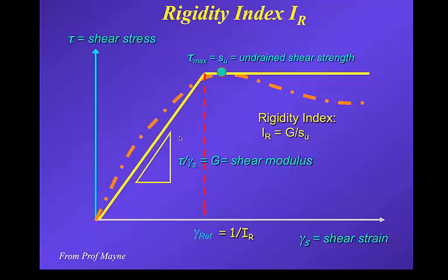And so in that 92 paper, we took data from a number of sites around the world. This was usually samples that were then taken to the lab. Consolidation tests were done, mostly in the vertical direction, and then some assumption of switching it to the horizontal based on the ratio of vertical to horizontal permeabilities was made. And the data is compared to the theory, and you can see a pretty good fit in general.